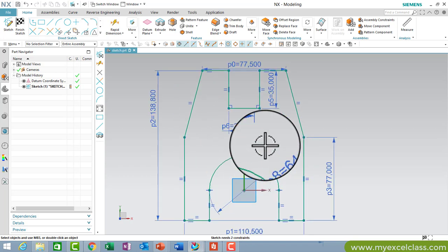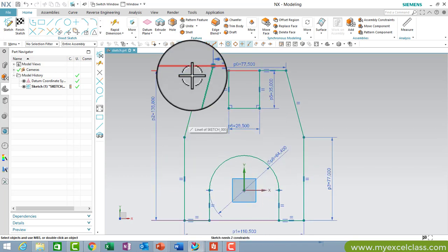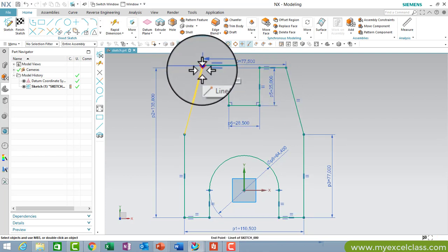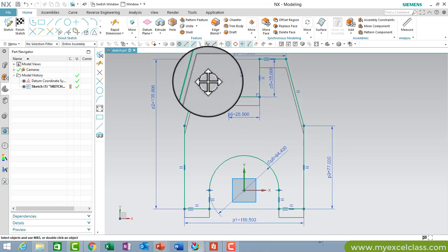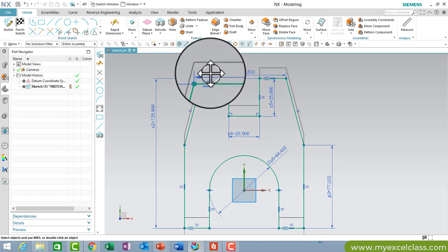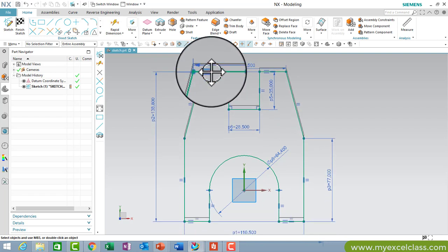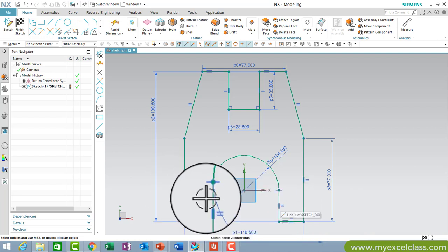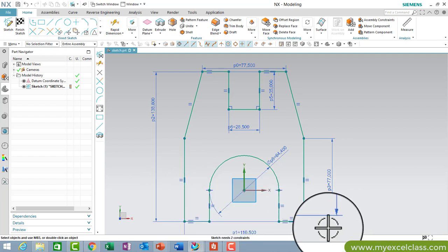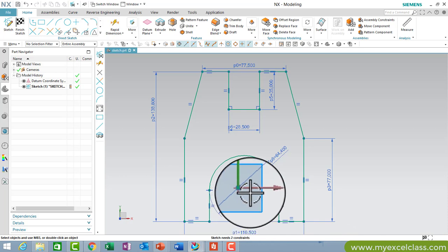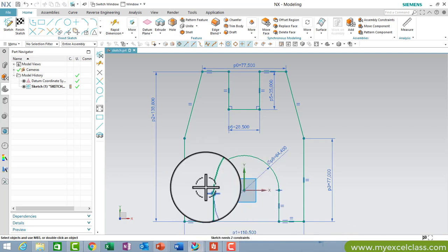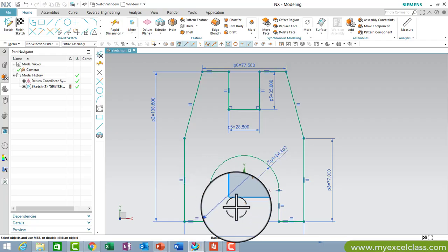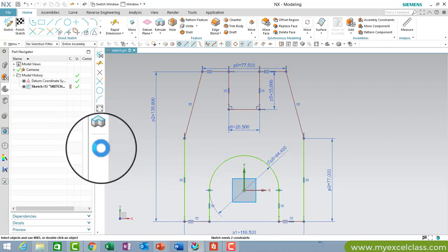Okay, and what I'm going to do right now is zoom out. I'm going to try to drag the points to check for the constraint. If you see, I'm able to move it up, right? So basically this length, like I said before, is not constrained. Though it's equal length, it just needs the value. The value got deleted when I trimmed the line. We had given this value before, if you remember, the 28. So that got deleted.